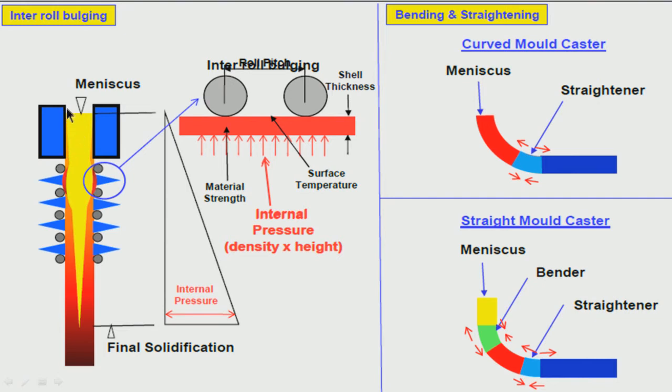It is melting here at the top, you are adding powder at the top, powder is melting, slag is forming, slag will be just above the liquid steel, and because of the oscillation, that is another important requirement of oscillation, some amount of liquid slag will be pushed inside here at the interface between the mold and the solid shell.